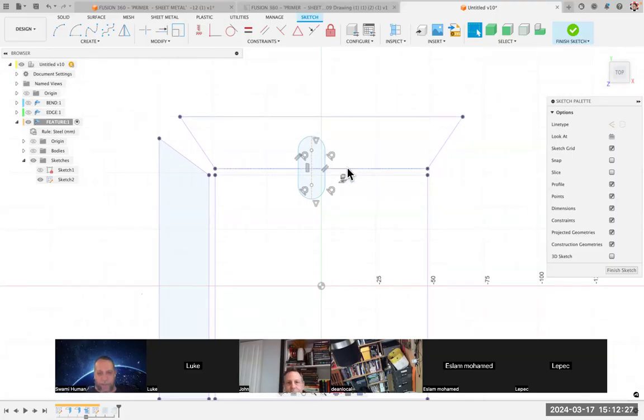And I just wanted to make sure in this illustration case that I was spanning the bend, right? Because that's the whole point of this one, is to show how we make a feature that goes across a bend. And again, it has to be done when it's flat, so that when you actually cut the thing on your machine, this is what you're doing. You have a flat piece of material and you're cutting that slot through it, so that all of the cuts are going vertical and down through the material in the right way.